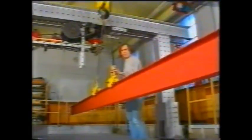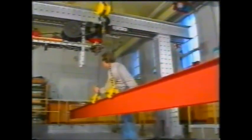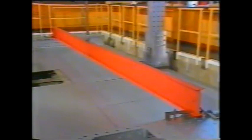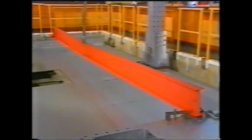The second beam is 7 metres long and is much more slender. The load is applied as in the previous test. Observe the response, shown again in an accelerated manner. It can be seen that significant lateral deformation and twisting occur, in addition to the in-plane bending displacement.